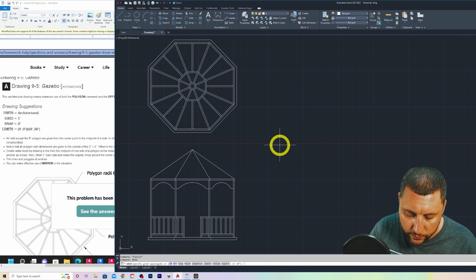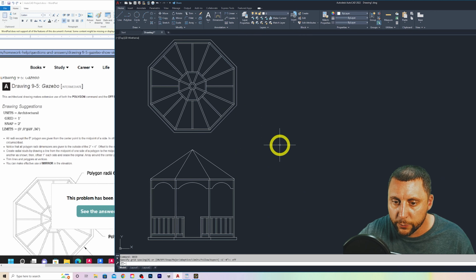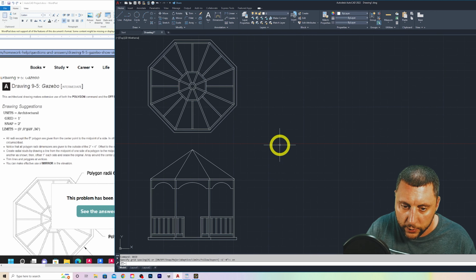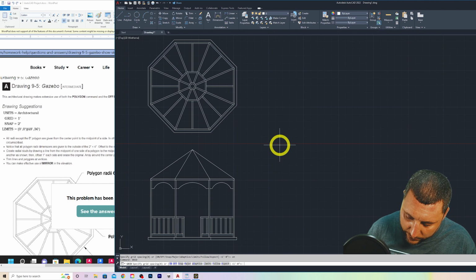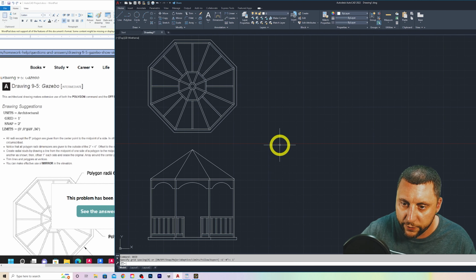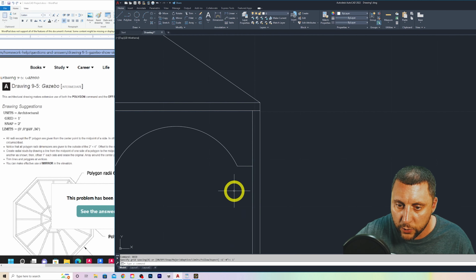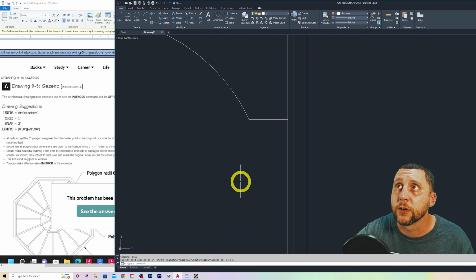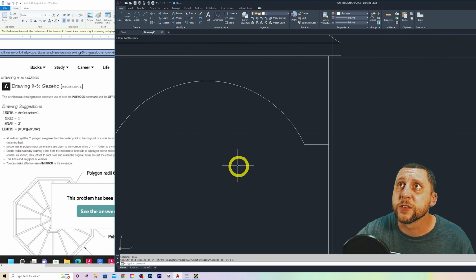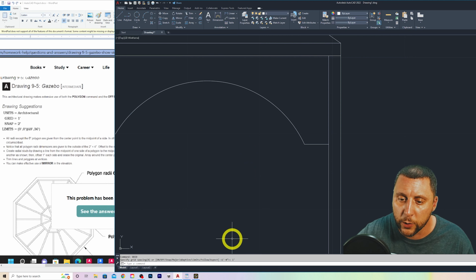Grid, you can turn that grid off if the grid bothers you. Grid on. You can type the distance or the size of each box of the grid. So if you type 1 foot, that means every single one of these little gray boxes, if you can see it on the screen, it's kind of hard to see, but there's one box here, and that would mean that that is 1 foot by 1 foot, okay?